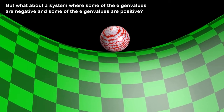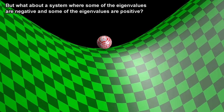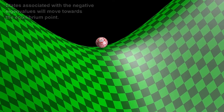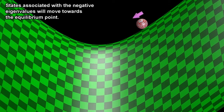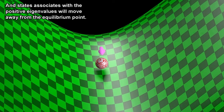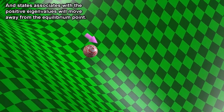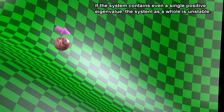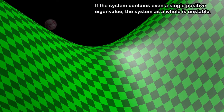But what about a system where some of the eigenvalues are negative and some of the eigenvalues are positive? States associated with the negative eigenvalues will move towards the equilibrium point. And states associated with the positive eigenvalues will move away from the equilibrium point. If the system contains even a single positive eigenvalue, the system as a whole is unstable.